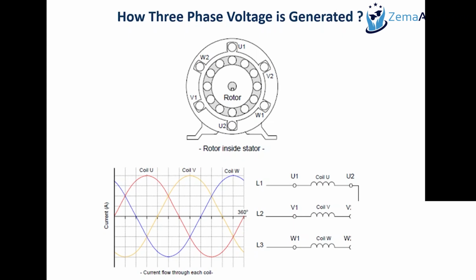If you want to achieve a 4-phase system or 6-phase system or 10-phase system, we call them polyphase systems. Yes, it is absolutely possible to generate 4-phase, 6-phase voltages. But we need to know why we need to do that. Because the 3-phase actually allows us to transmit or transform the power from one point to another point cost effectively.